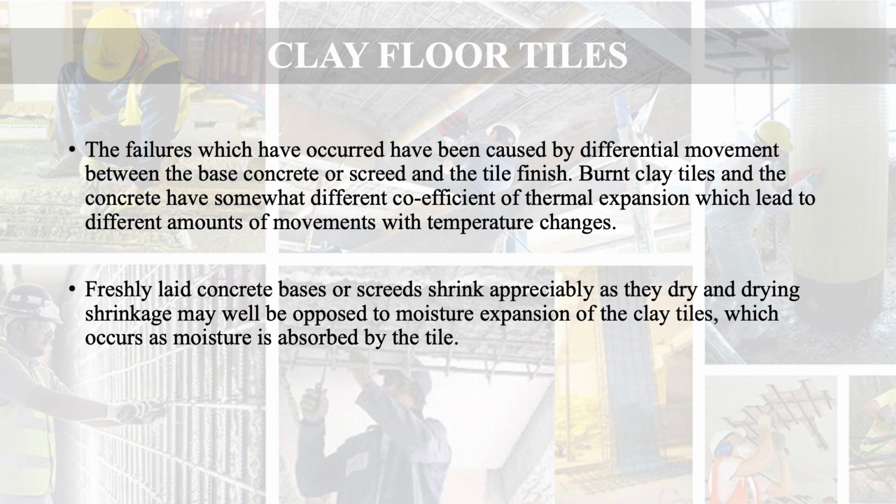Freshly laid concrete bases or screeds shrink appreciably as they dry, and drying shrinkage may well be opposed to moisture expansion of clay tiles, which occurs as moisture is absorbed by the tile. It means one thing is shrinking, another one is expanding. So the two effects are of different nature.